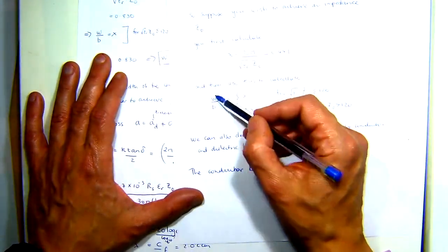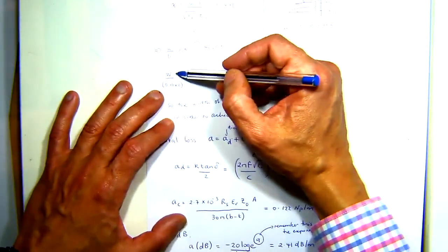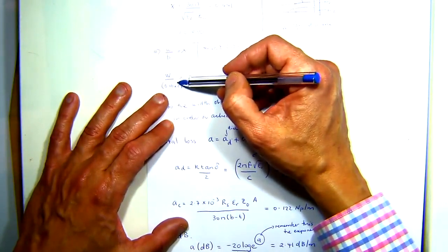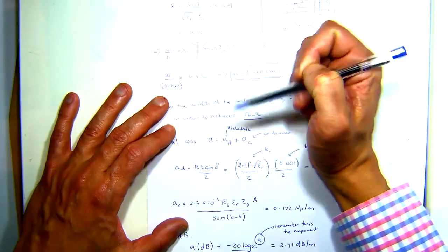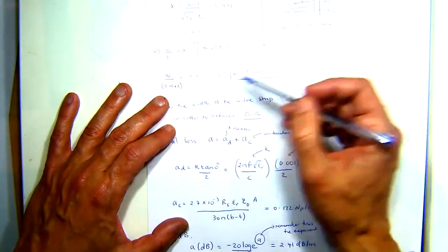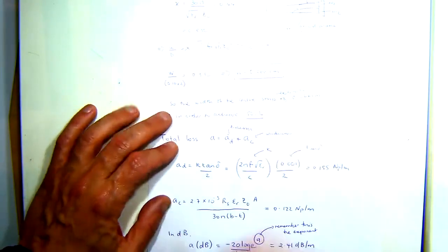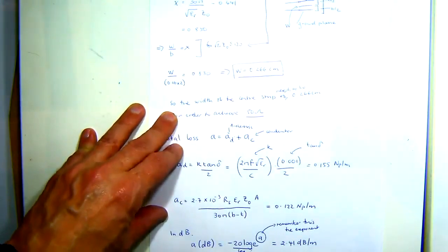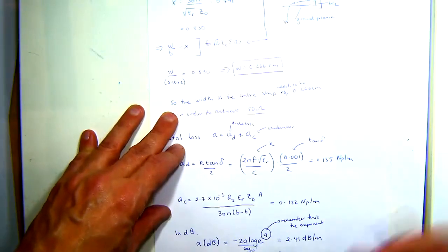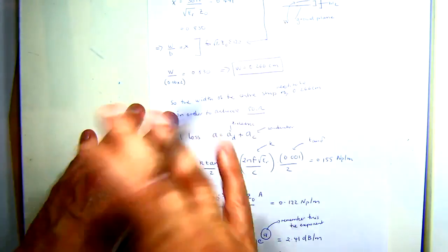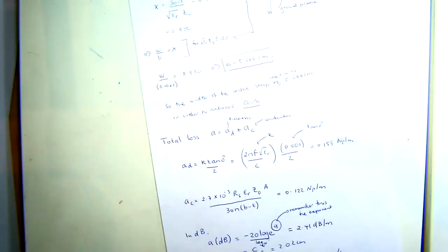X is equal to W on B. I don't have to make that correction. I know what the thickness between the two ground planes is. We said that the thickness of the material was 0.16 centimeters. So the width is actually 0.266 centimeters. Now here, you just got to be a little bit careful that I'm actually using all centimeters and millimeters. If I'm plugging it into certain things, you just got to make sure that I'm dimensionally correct, right? So just be a little bit careful there.